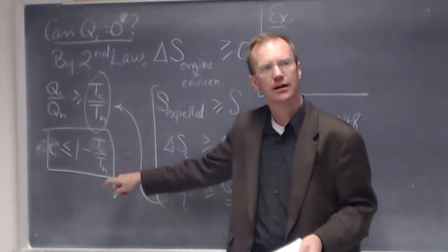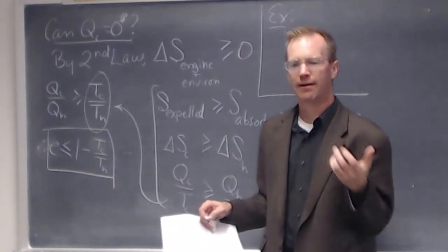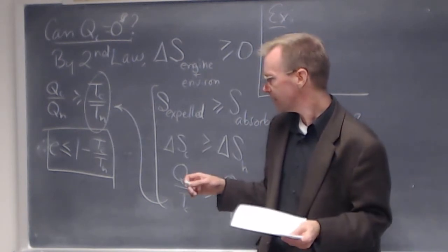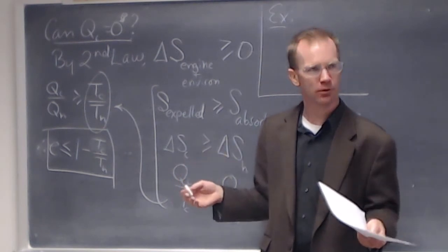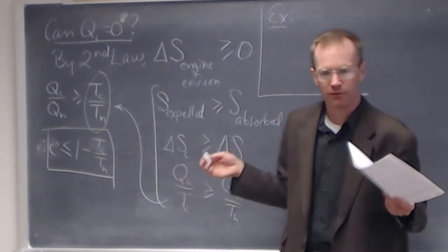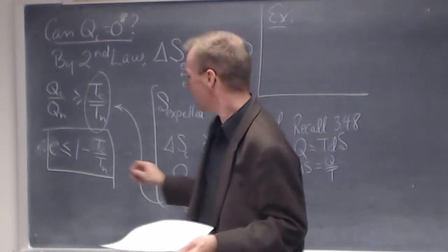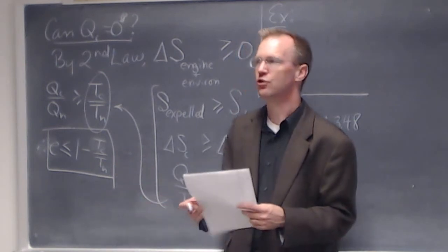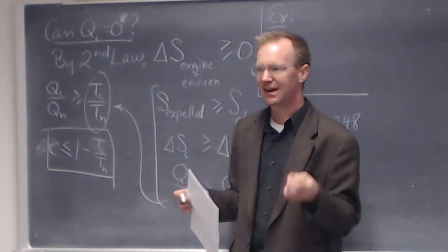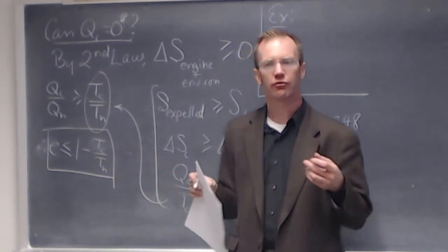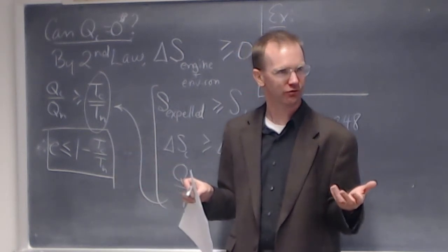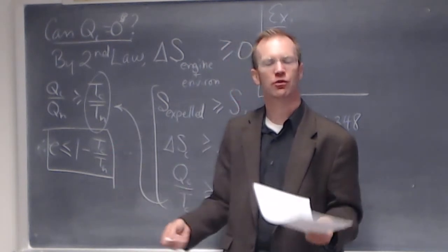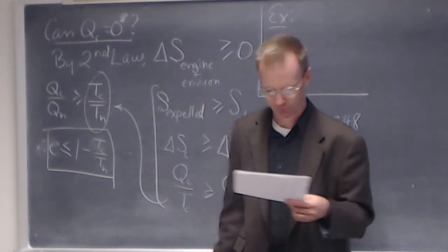TH, on the other hand, is determined by whatever it is you're using to generate heat, and that is partly a matter of what fuel you burn, or whatever other source of intake heat you've got. It's also determined in part by metallurgy. Your engines are generally going to be made out of metal. Well, you can't have a high temperature that is so high that your engine melts or deforms or whatnot. So, the upper limit on TH is determined by metallurgy and by your fuel source.